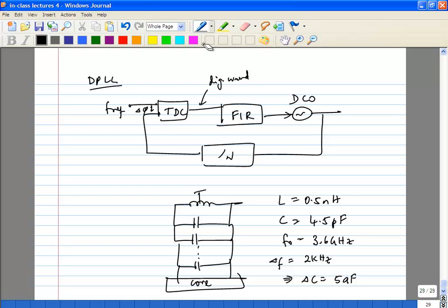In other words, earlier your loop filter R, C, all those things vary over process if you implement on-chip loop filters. If you have an off-chip loop filter, it's obviously bulky. You need to reserve a pad to go out, and you need to worry about the inductance going out into that. A lot of issues. Having a completely on-chip digital filter would make things very nice, because the bandwidth of that filter will be very fixed over process and temperature. It doesn't matter because they're just numbers at the end of the day. That is the main motivation.